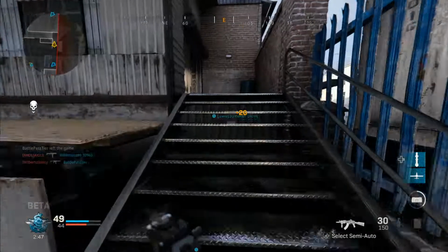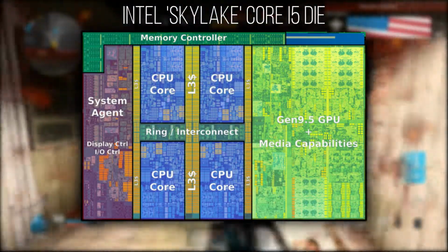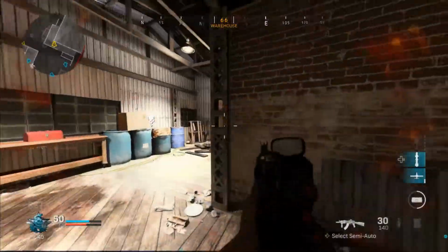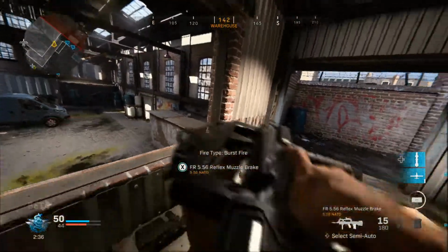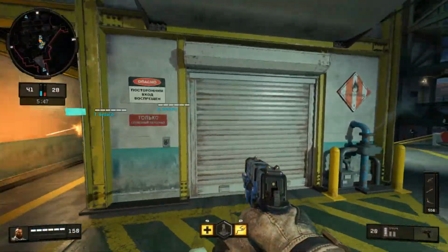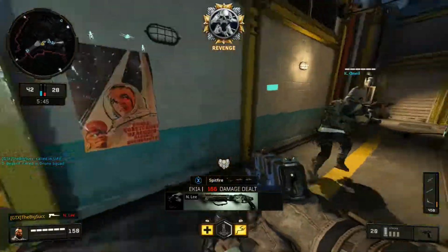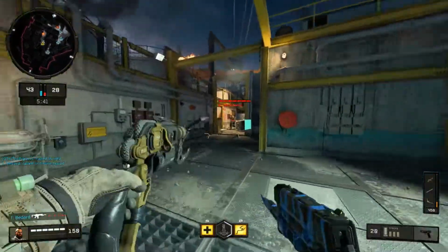Now, in a real-world chip, this bus is generally at least 64 bits wide in an x86 64-bit chip, which makes these chips able to transmit larger datasets and improve efficiency per cycle, but it's incredibly more complex. However, when it comes down to it, the bus inside the chip doesn't actually do any data processing. That's all done by the transistors.